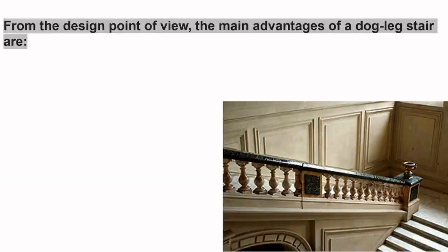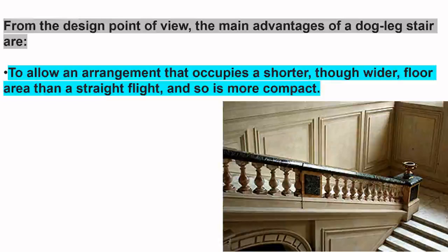Now, from the design point of view, the main advantage of a dog-legged stair is to allow an arrangement that occupies a shorter though wider floor area than a straight flight and is more compact.